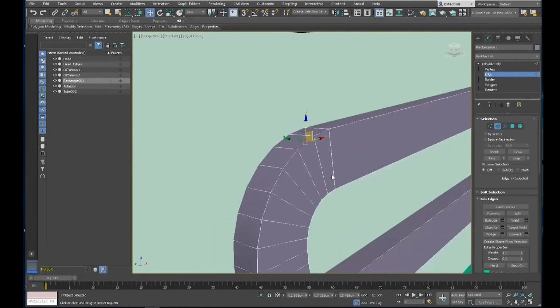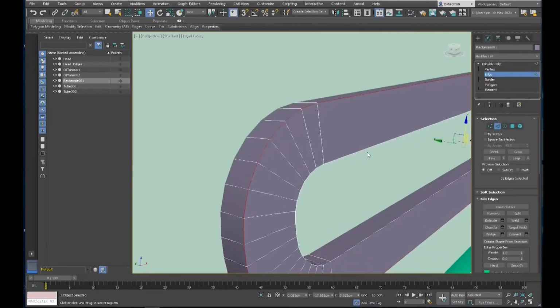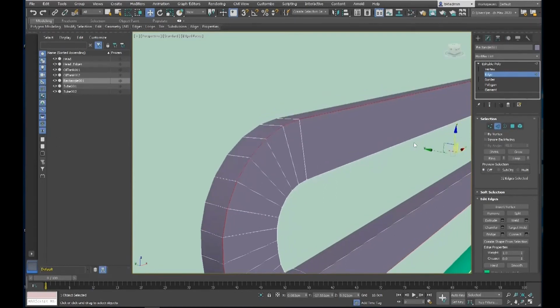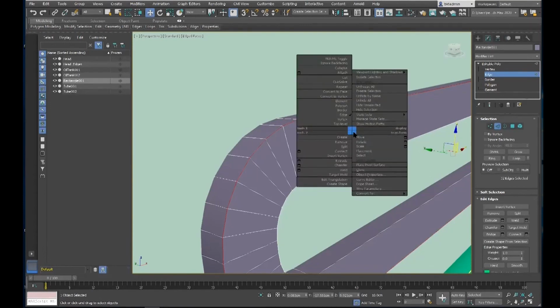that's going around. And can you see on the right side in the selection area, we have a loop as an option. It has a hotkey, that's Alt L, but we will not use it yet. So loop. And once you have loop, we will use the right-click menu. Edge is selected, press the right-click in the viewport, and hold on for a second. If you see this quad menu, that's okay. If you don't see it, please make sure you have edges selected, and press the right-click.